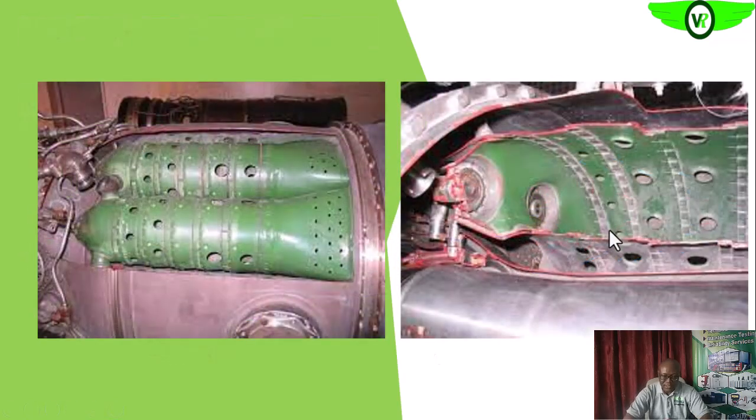Over the combustor. So this is how you see it physically. These are the perforations or the openings into the combustors that the cooling air will go in through. So this is a cutaway view. This is the section where the secondary air flows through. This is it. Then the primary air comes in through here.